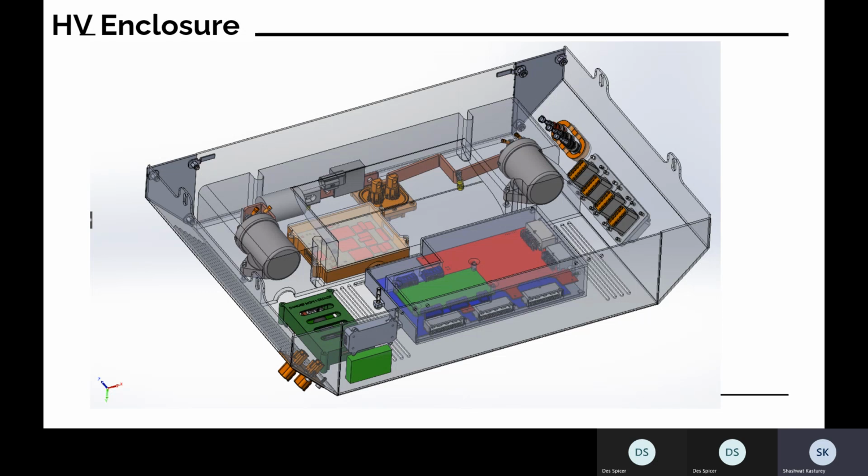This connector bank in particular is 12-volt power out from the car. That 12-volt power comes from a DC-DC converter. The DC-DC converter takes the 400 volts of power from the battery pack and turns it down into 12 volts. It's basically a solid-state transformer, as I understand it. Maybe Des can correct me on that. It's close enough of an approximation.